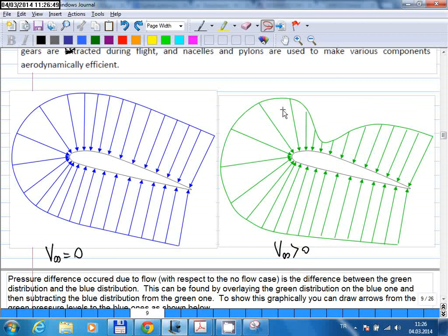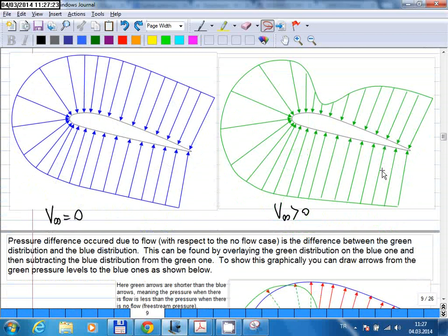By the way, these arrows can never be negative, right? There's no such thing as negative pressure. By definition, pressure is always a positive force, because the molecules hit the surface and create a force, and that force coming towards the surface is the positive direction. So there can at most be no pressure force, but you cannot really have negative pressure. The best that can happen is this green arrow becomes zero length in the ideal case, but other than that, you cannot have a negative pressure.